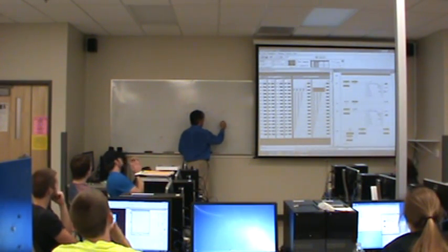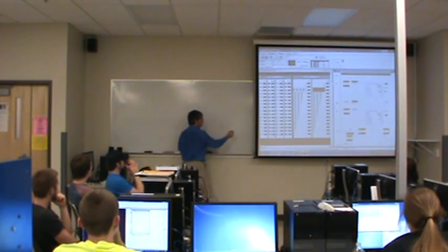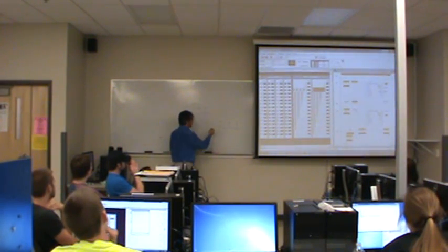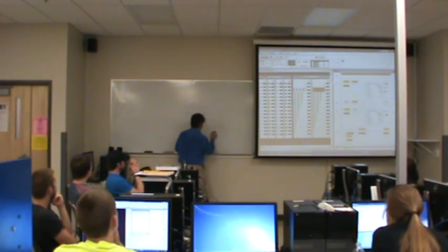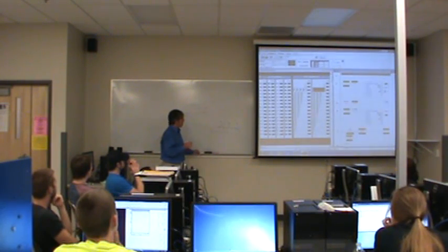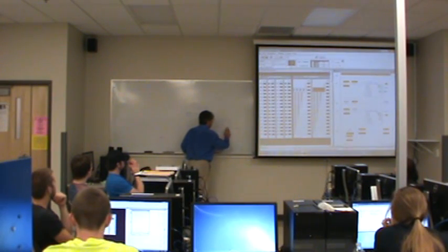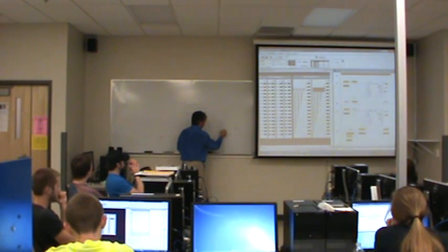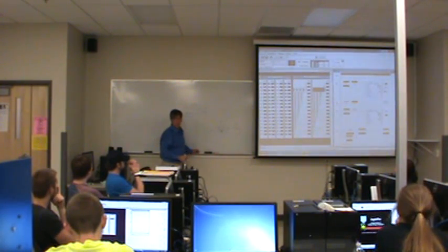If switch A and switch B are true, in other words, if they're both on passing power, then the output, let's call it Y, could be on. Okay, so to make the ECETs happy, let's put L1 here, and let's connect this back to neutral. So basically, switch A and switch B have to be on for Y to be true. Now, another way we could wire this up is in an OR configuration, so that if switch A or switch B is on, then the output would be on.